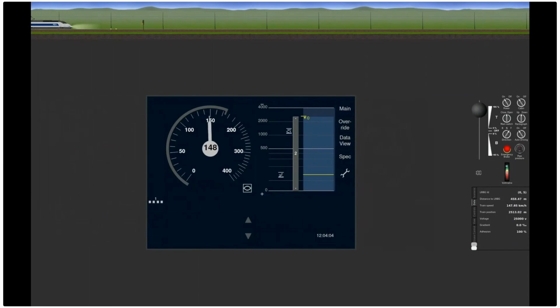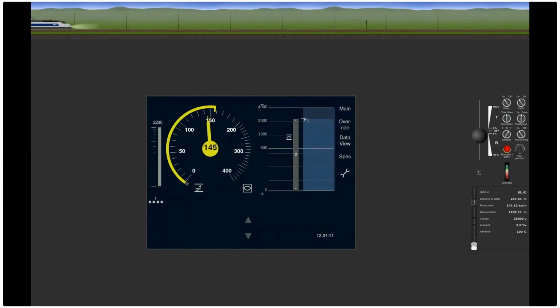For the second area where the pantograph will be lowered, the driver is informed to lower the pantograph by displaying the lower pantograph announcement icon. Then, the lower pantograph icon is displayed when the train is in the area. The pantograph shall be lowered. Then, the raised pantograph icon is displayed to inform the driver that the train reached the end of area. The pantograph shall be raised.